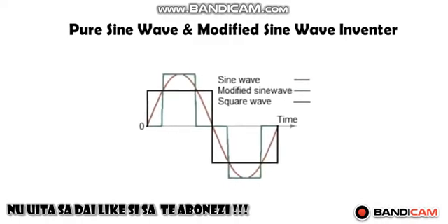The modified sine wave inverters are much cheaper than pure sine wave inverters, and that is because they have less circuitry. Modified sine wave inverters use transistors that act as switches, and they basically turn on and off the current to create a staircase pulse or a square wave. Appliances that use output from modified sine wave tend to overuse power and run hotter and thus inefficiently.